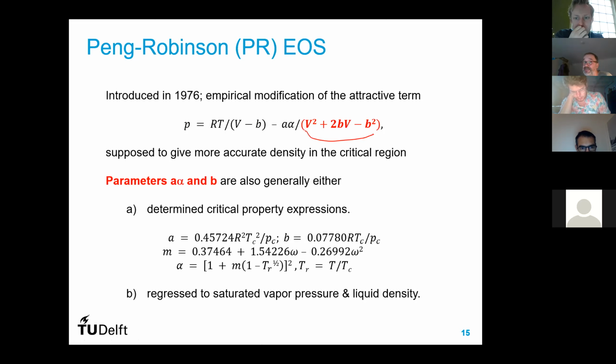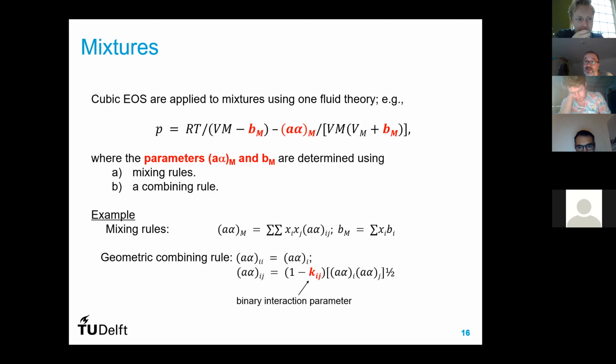But for modern energy applications, you need more and more complicated equations of state because in a lot of cases, we need to deal with brine, and brine is water with dissolved chemistry that wouldn't be predicted accurately using this Peng-Robinson equation of state. So there is some correction needed. One of the big questions is how you apply this equation of state for a mixture of gases.